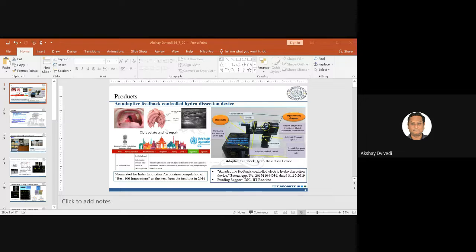I am just trying to highlight that there are certain issues and we have to understand those issues. So here, what we have is this electrolyte, and this electrolyte is, let's say, NaOH. So what you do is you have a liquid, which is water, you add a certain salt, which is NaOH, in it, and as soon as initial sparks come in, this spark will be creating thermal energy, which will be evaporating water out from this. So that zone near the tool will be having the maximum rise in temperature.